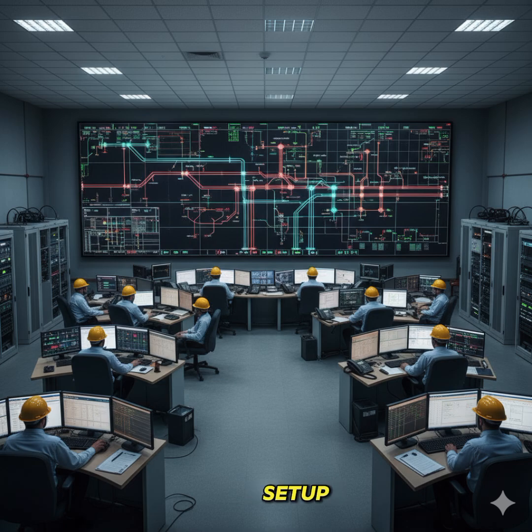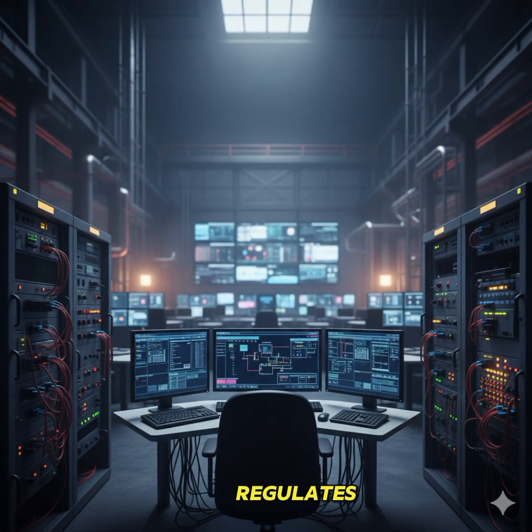In a DCS setup, the plant is divided into different sections, called process areas or units. Each section has its own dedicated controller that handles the control logic for that part of the process. For example, one controller might manage a boiler, another handles the distillation column, and another regulates a reactor's temperature. All these controllers are connected through a high-speed communication network and report to the operator stations in the control room.